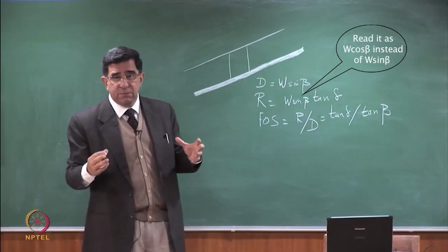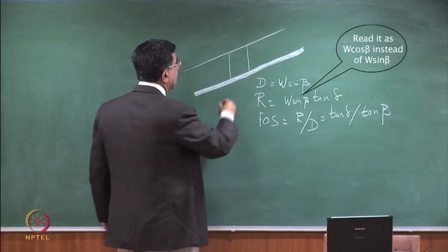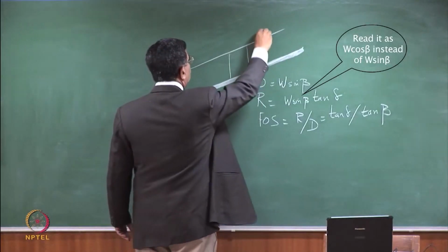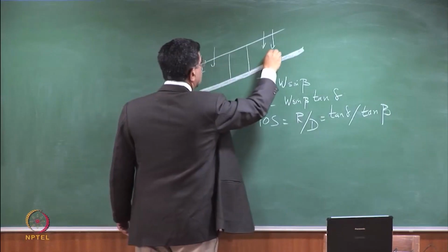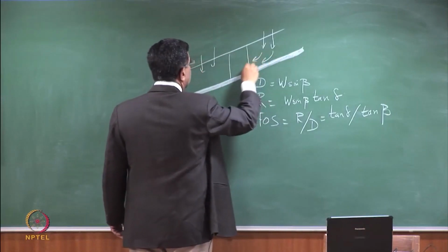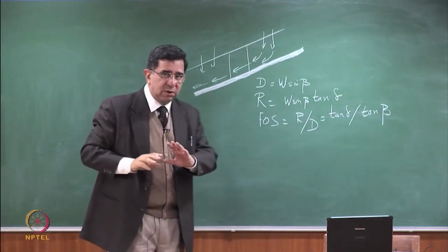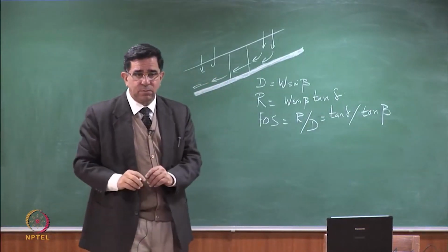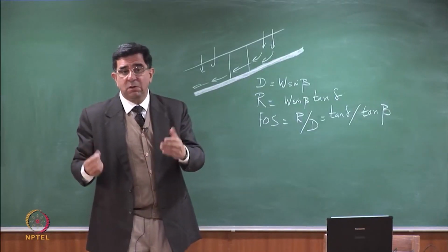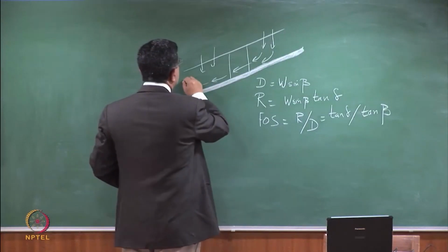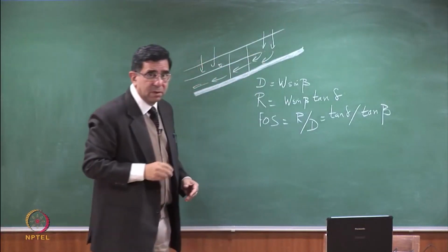So, you have to set up the free body diagrams, and I am not going to get involved in setting that up, but remember seepage force, rainfall, it is stopped here, therefore it begins to go like this, and therefore the seepage force or the drag of the seepage force is downslope. It causes instability. How much instability it will cause? It will depend how much water is inside the system.